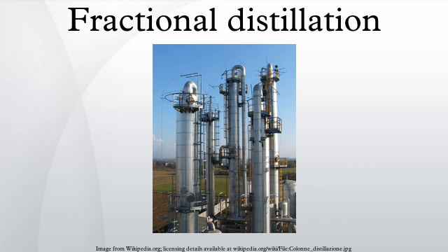Industrial distillation is typically performed in large, vertical cylindrical columns known as distillation or fractionation towers, or distillation columns, with diameters ranging from about 65 cm to 6 meters and height ranging from about 6 meters to 60 meters or more. The distillation towers have liquid outlets at intervals up the column which allow for the withdrawal of different fractions or products having different boiling points or boiling ranges.